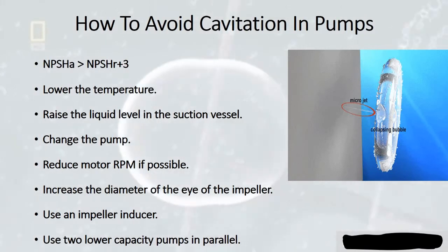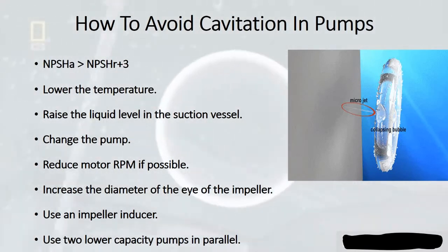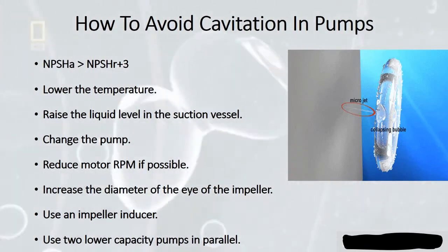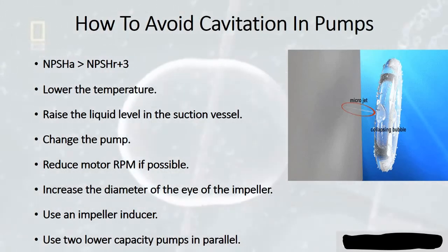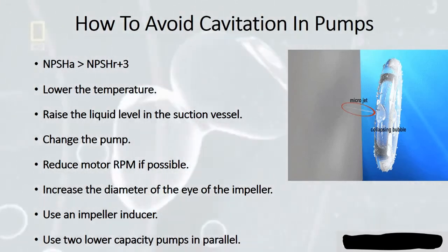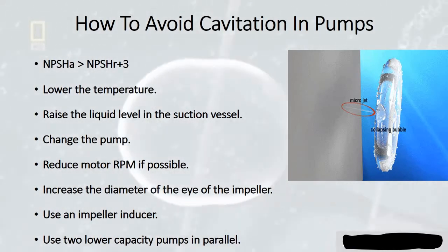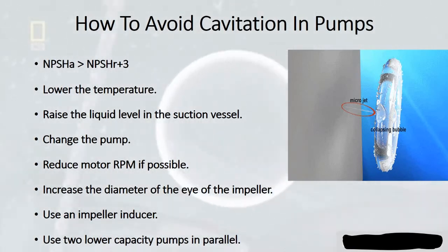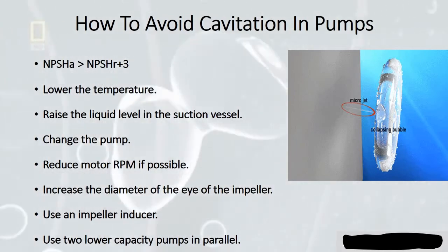The most common cause of cavitation in pump installations is pump discharge requirements specified above the actual requirements of the installation. From the performance curve data, it's obvious that the tendency toward cavitation increases as the pump head drops or as the capacity increases.